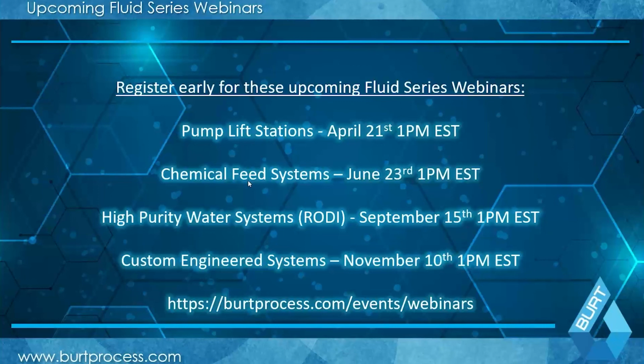In addition to that, different types of oil can also have a coating impact on the instrumentation involved in the system, which could be detrimental. So it's probably advisable to actually remove the oil upstream if you can, into something like an oil water separator, just because of the coating nature. Now, trace amounts happen all the time. People put that in, but if you are seeing a fairly large amount of oil, I would remove it before bringing it into the system.